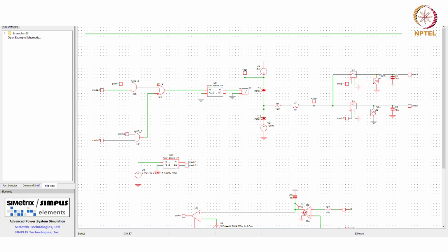Okay. So discontinuity is always there. You cannot say that the V out equals D times V in formula is gone completely because of these switches. So now you just have to maintain that the average inductor current in each phase is what is required by the load. And if that is getting disturbed, then the extra current you have to throw out by adding a freewheeling switch.